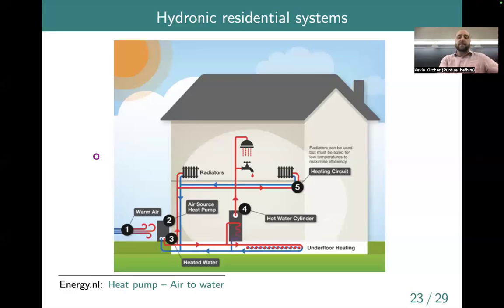But yeah, so the question is, are these radiant heating systems more efficient? And the answer, I think, is not in general, not necessarily. One thing that they have that most US systems don't have is a lot of thermal inertia, a lot of thermal mass. So you'd heat up this big block here. And so you could imagine that leading to a lower cost, although not necessarily lower energy, system. If you could heat up all that thermal mass when electricity is cheap, and then do less heating, but still get a lot of radiant exchange when electricity is expensive, then it might lead to a cheaper system.